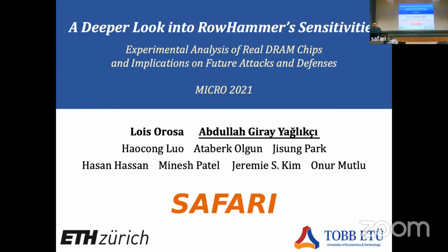You mean like how RowHammer happens? Yes. In the literature we have different circuit-level or physical models that explain how RowHammer happens. Basically, you have different error mechanisms based on charge leakage and charge trapping. When you hammer one word line, it can create an electric field around it, and then it can drift some electrons, and those electrons get stuck at some points that exacerbate the leakage.